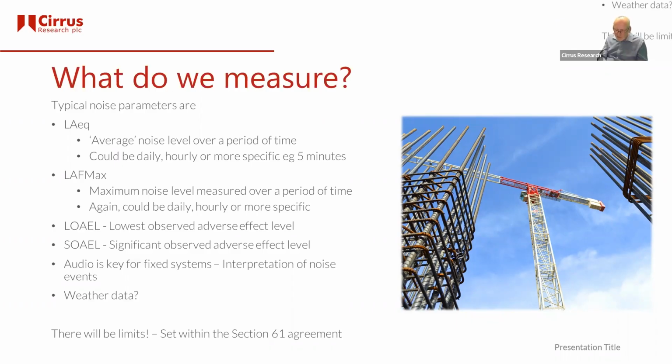The other two I've put down there, these aren't measurements themselves, but I just thought to mention that some larger projects can use things like the lowest observed adverse effect level, LOAEL, or the significant observed adverse effect level, SOAEL. These are set levels in large projects that people will be asked to report on, usually based on the LAeq over a particular period.